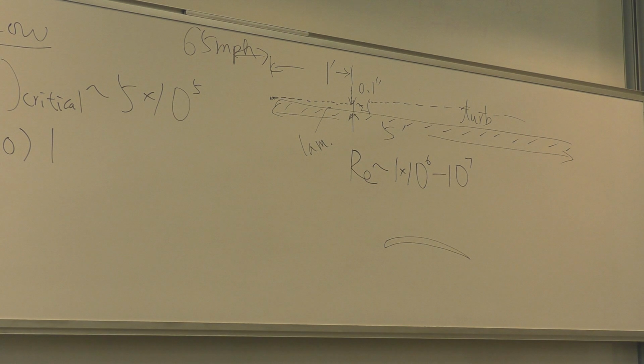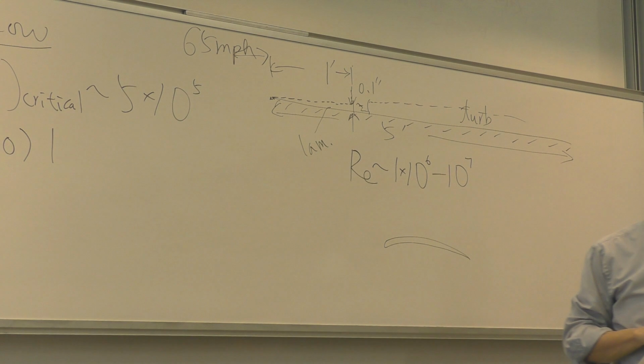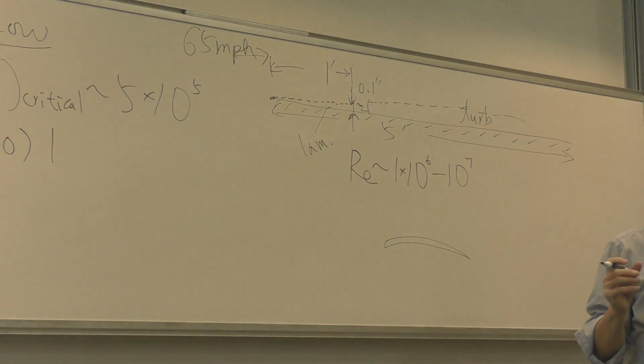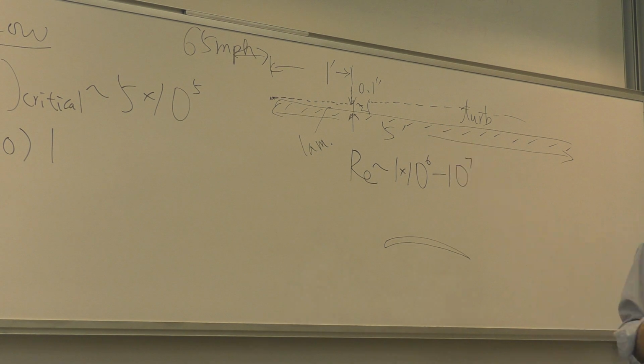Do you have a feel for that? So this transition is different from internal flow in the pipe, where the flow can be either purely laminar or purely turbulent inside the pipe. It always, for external flow, has to go through laminar to turbulent. And that has some important consequences to engineering devices, which we will alert to today. But let me pause and make sure you understand this concept of transition on the external flow.